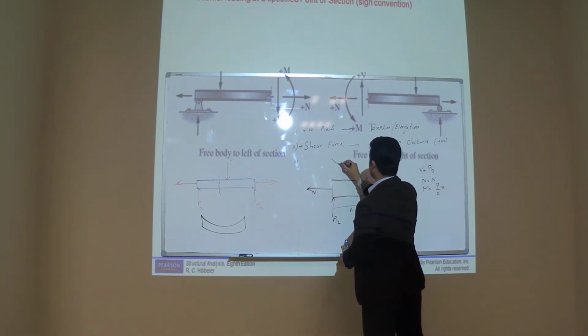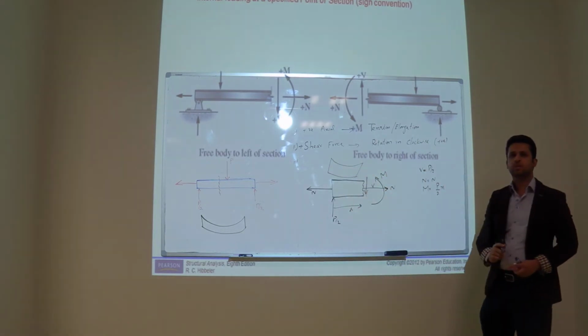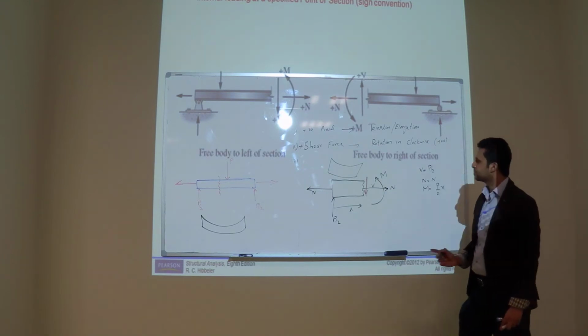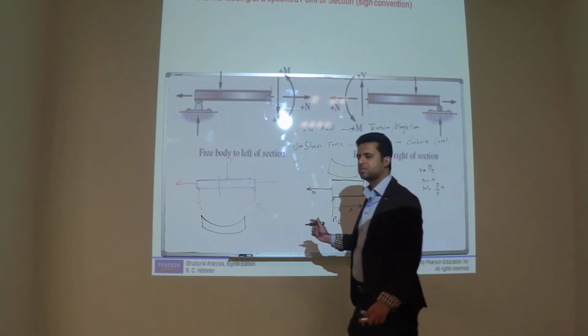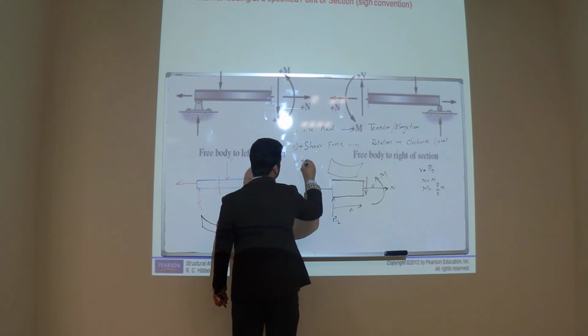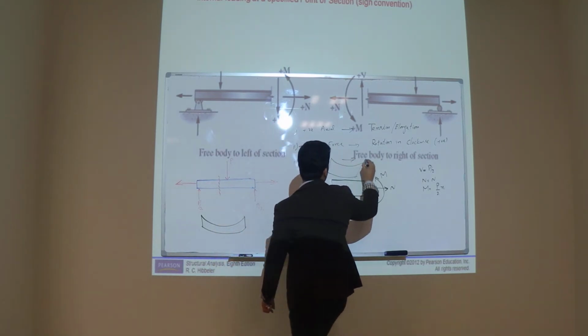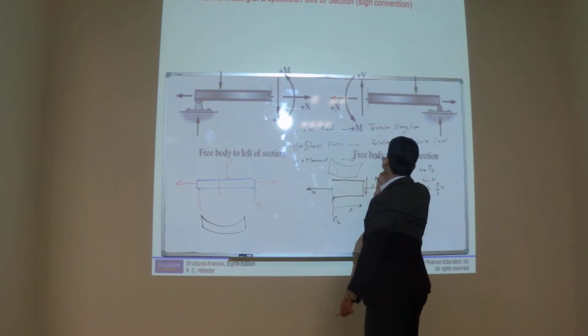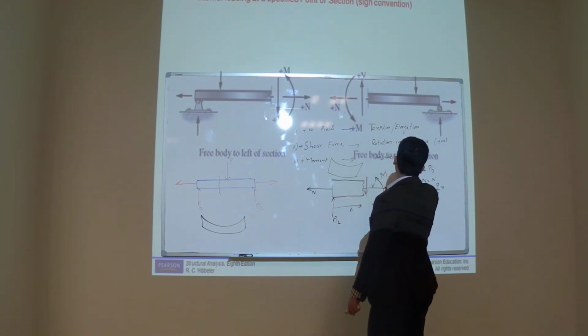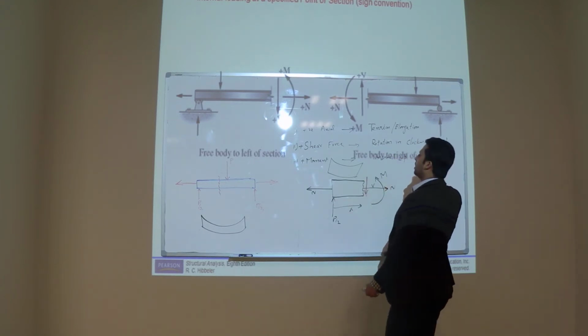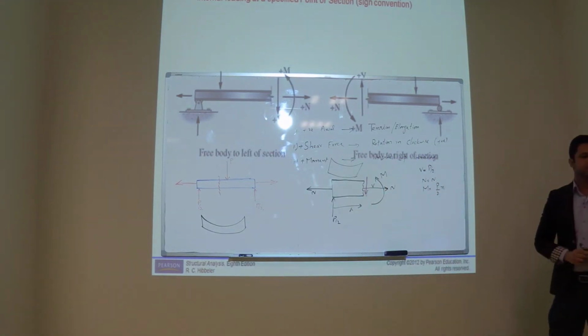This moment will try to bend this segment like this. Concave up. So positive moment is concave up bending.